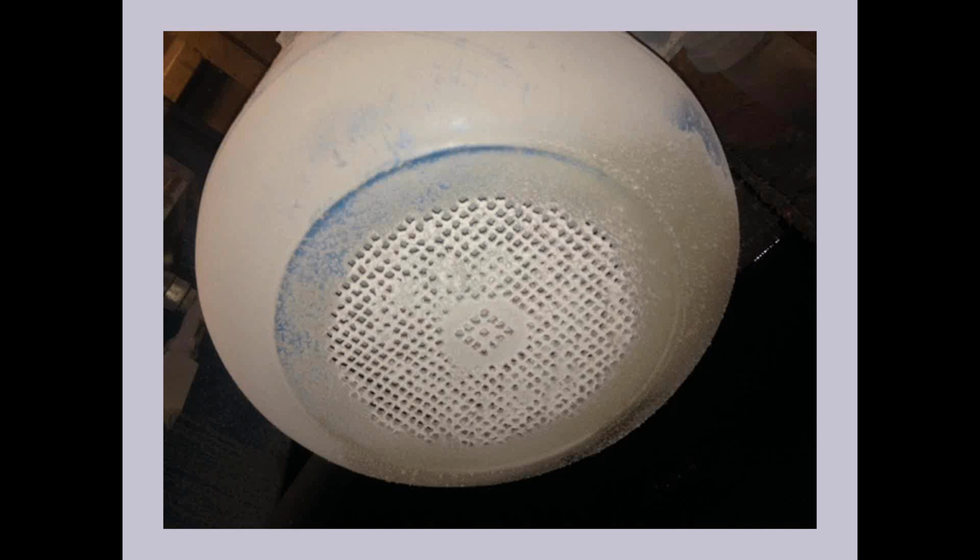Well, let's look at this picture. Why would this motor here fail at a faster rate? Well, again, here the screen on the back of the fan guard is covered. It's not getting the correct air across the motor. And the failure mode for motor insulation is that for every 20-degree F rise in the temperature of the motor windings, it cuts the insulation life in half. So by keeping the back of this motor guard clean, we get more air across the motor, we cool the motor better, and we extend the life 2 to 3 times.